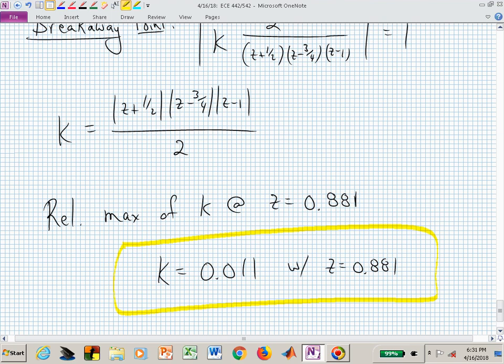What we would like to know maybe is, have we already snuck out of the unit circle at -1? It's not too hard to calculate the gain k at -1 because we already have the formula for k. So let's compare what gain it takes before we escape out of the unit circle at -1, because we need to figure out where those branches are relative to the unit circle and what magnitude of gain k gets us to those points.